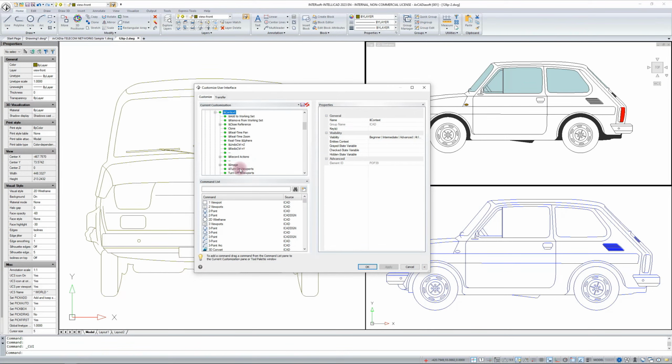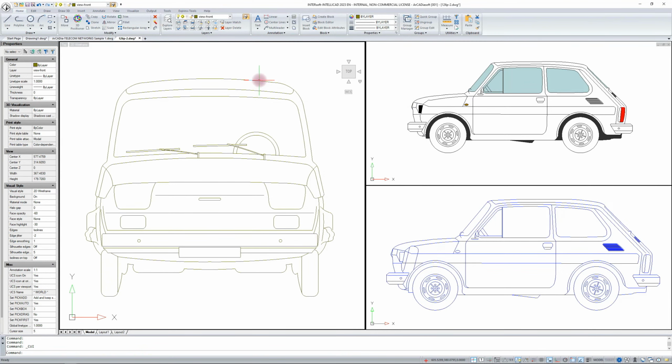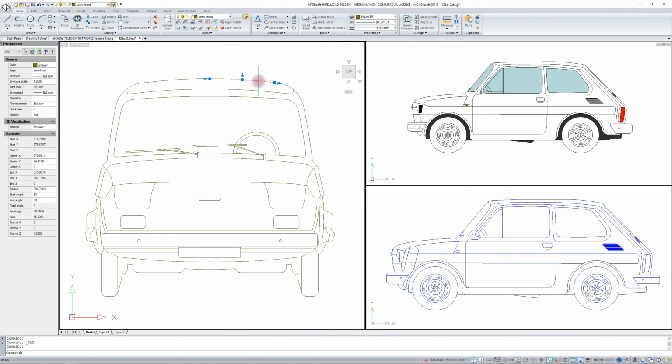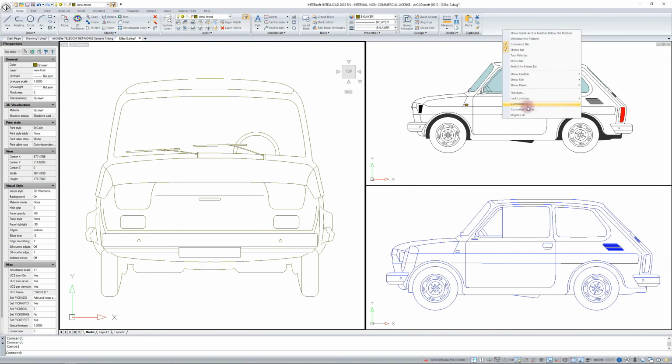So if we want to change anything there, we can also add or delete it here. Here you see all the options that can be found in the context menu. Let's check, maybe before we add something there, what we have under the right button. And we can customize our options, remove those things we don't use, and leave those things that we do use. Or add something that is, for example, not there. I see here that there is no offset option. So that is this modification option here. We will add this one for ourselves and go to the Customize window.